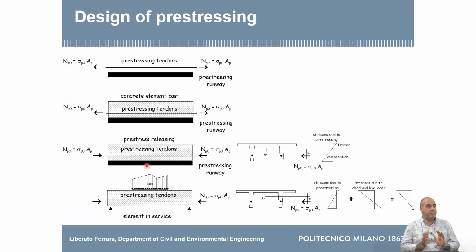Well, this is a very simple scheme. You will see Saturday when you go to the factory, there are these pre-casting yards that are like runways, okay? And on those runways, depending on the shape of the cross-section of the element that you have to cast and design, you will lay down some pre-stressing tendons, which are like cables, steel cables generally. They are loose ones, okay?